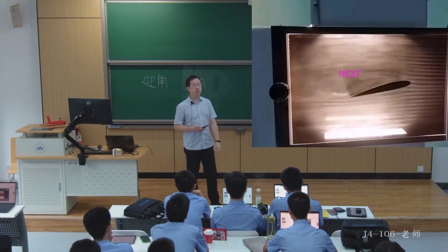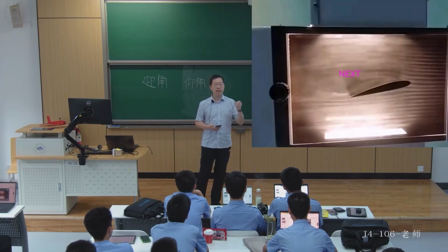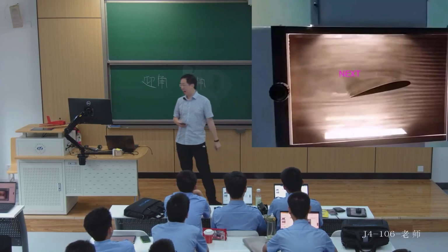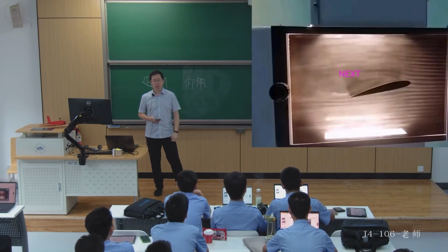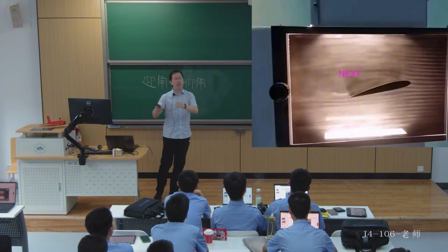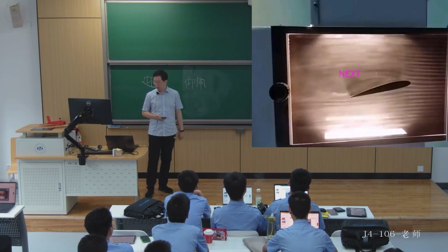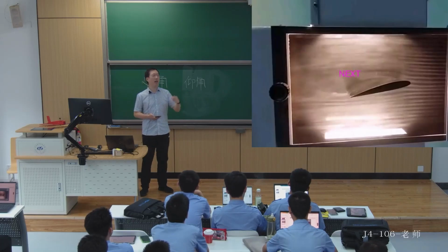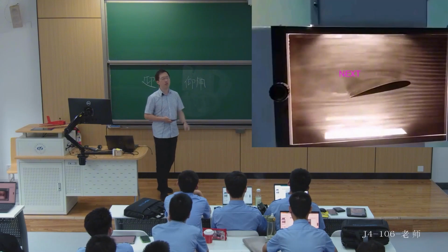How much impact does the Reynolds number have on an aircraft? In fact, the Reynolds number mainly reflects its magnitude's impact on the aircraft. Specifically, for example, for a flying object with a relatively small Reynolds number, like a butterfly in flight, combined with its speed, it is at the level of 10 to the power of 3. For a seagull, it's larger, around 10 to the power of 5. And for our small drones, it's also approximately 10 to the power of 5. When it comes to general aviation aircraft, it reaches the level of 10 to the power of 6.